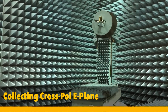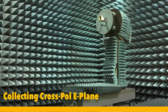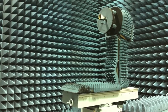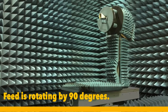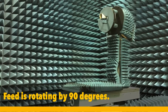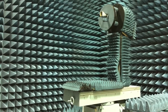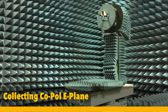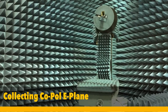So yeah, that's our cross pole. We go now to +90. Now it's going to stop here, and now you're going to hear a noise in the background, which is the rotation of the feed to make the polarization match with the E-plane. Okay, now the polarization is matched, and we're going to do our last cut, and this is copole E-plane.